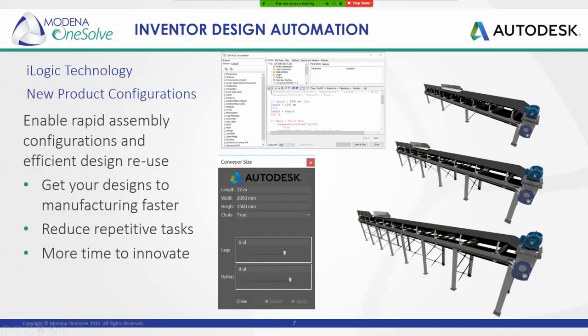This is an example of a product configurator for conveyor that was created using iLogic. Now, let's say a client has come to us requesting a custom conveyor size. We can easily reference this form to make the requested changes. So you can see in the top level, we have some parametrics over here that can be adjusted. So we can change the length, width, height. We can also decide whether we want to include or exclude other components, such as a chute.